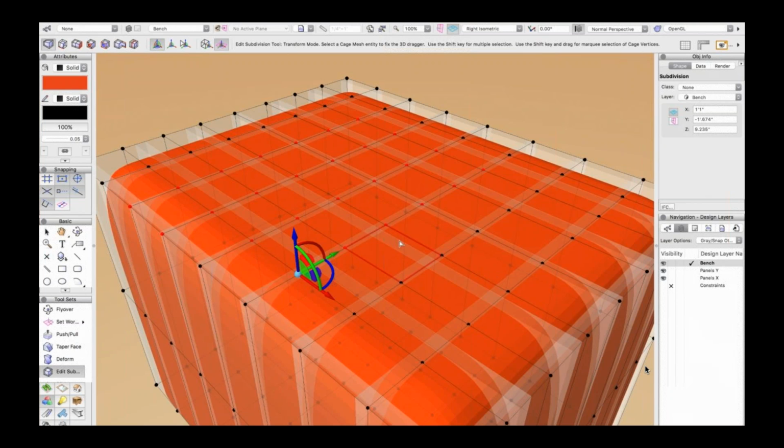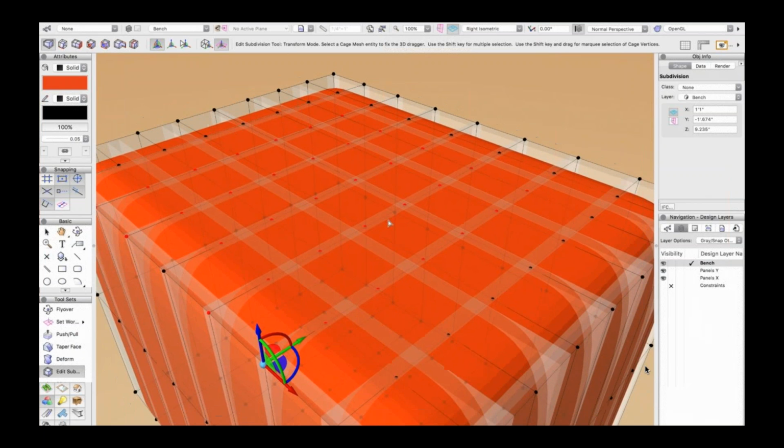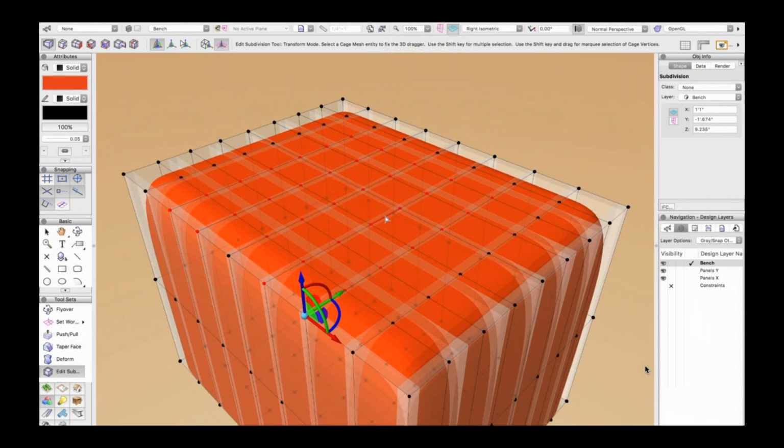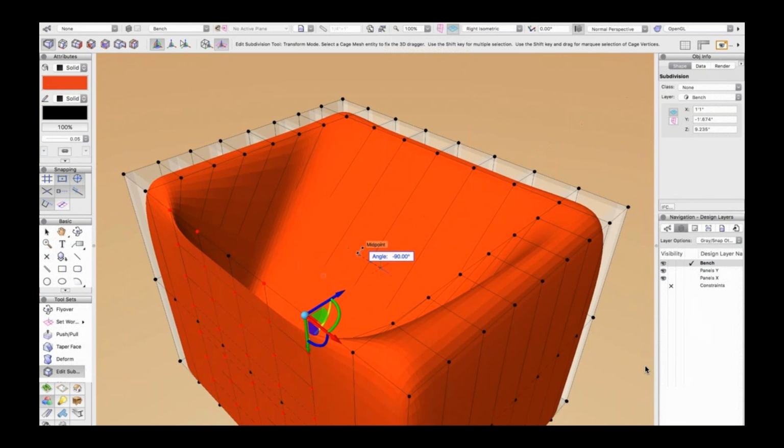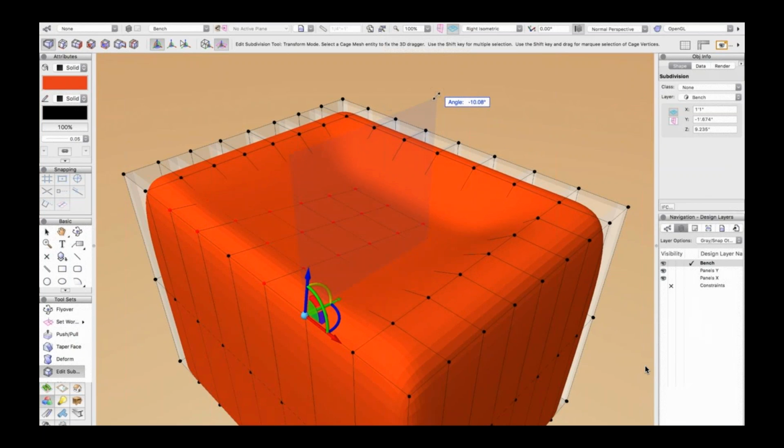Another thing that, again, I just want to reiterate, I'm being really careful to select just the points and not the edges and faces beyond. And there is that ability to do that because, as you notice, that object is a little bit translucent. And when you're in this edit phase, you can actually accidentally pick a point or an edge or a face that is beyond the surface that you were intending. And that could get a little bit messy. If you, say, select a grid like I've done here, and you decide to rotate it, well, other points and surfaces elsewhere in the object might be rotating. You might not be aware of it. Well, that compounds a lot in the future if you're looking to clean up your messes.